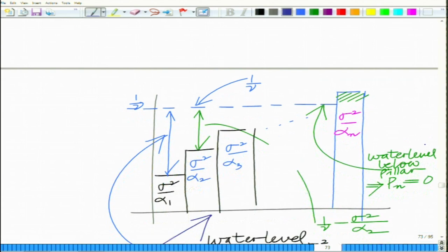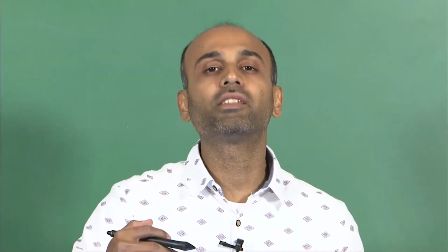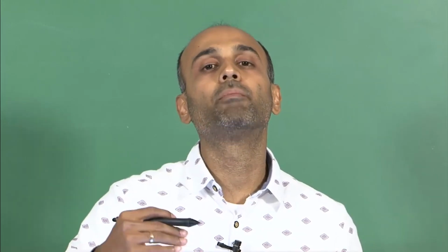Now what we want to do is come up with a framework for optimal power allocation. Remember, we have seen the optimal power allocation problem: we have a total transmit power P, and a set of parallel channels each given by gain alpha i, and we want to allocate the power optimally amongst these parallel channels so as to maximize the total bit rate that can be transmitted, that is the sum capacity, the sum rate of this wireless channel. That is the problem of optimum power allocation.